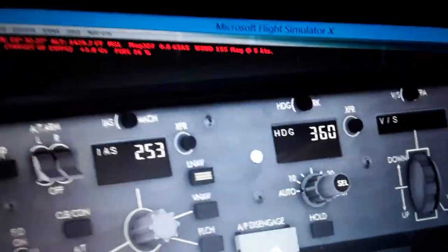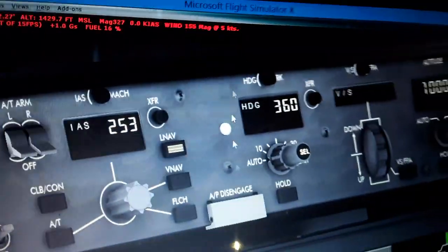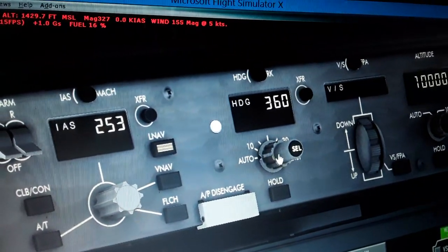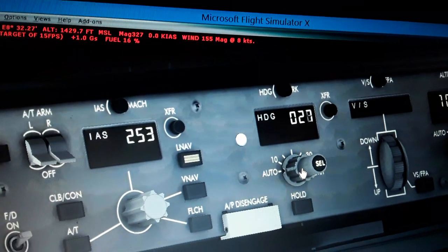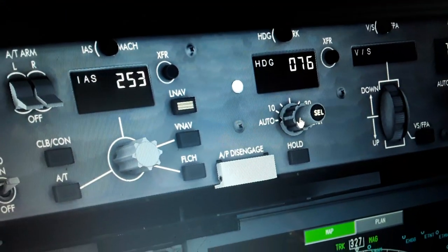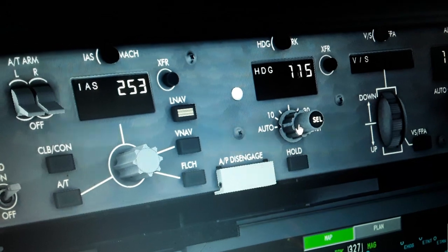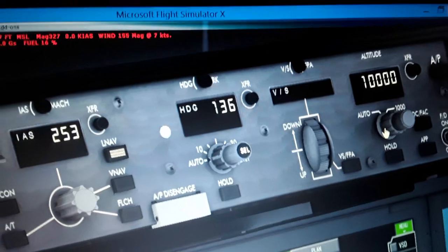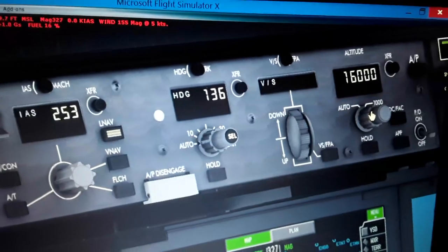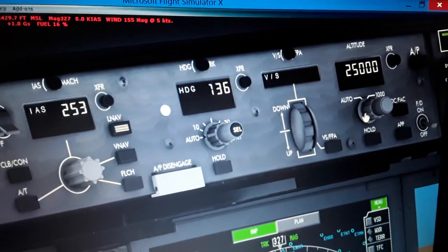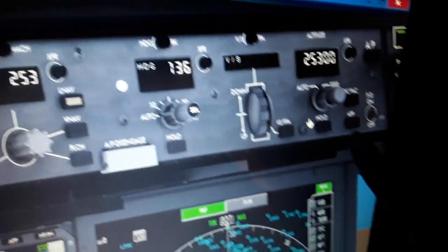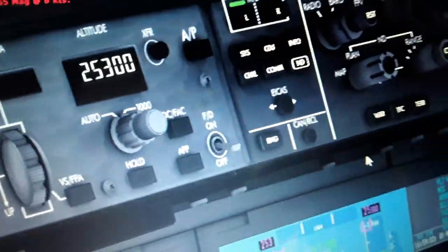of the aircraft, the bank angle, and you can use auto or manual. The heading, we're gonna use the magnetic north pole heading of the runway, 136 degrees. The altitude here we're gonna change the altitude we're gonna fly. Altitude. We're gonna change it again. We have the VOR localizer, the approach for the autoland function over here, as you can see.